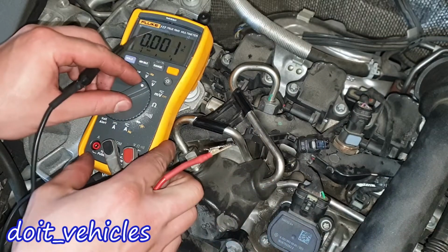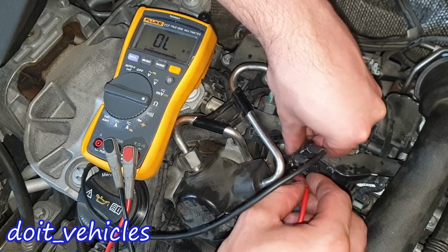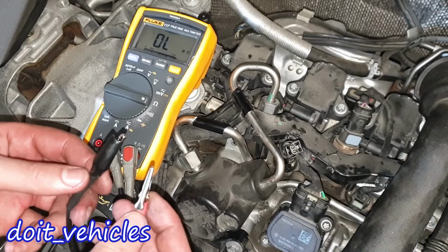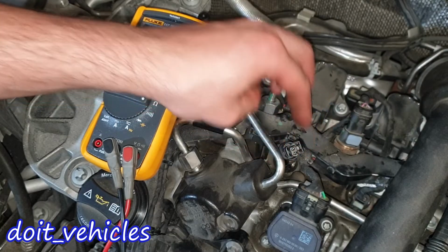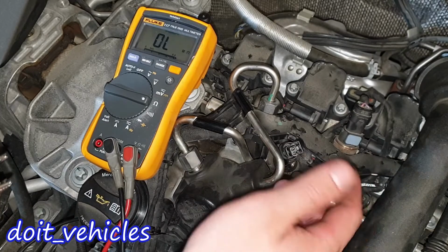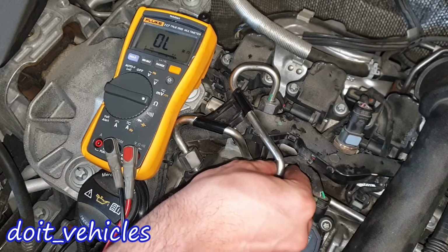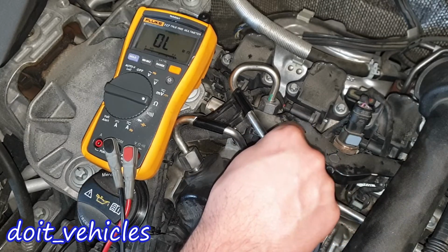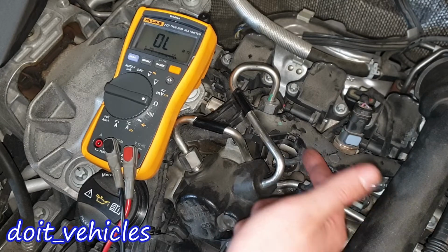Yeah. So let's turn this to ohm reading. We should find something between 3 ohms and 13 ohms. Okay, 1.5 ohms. It's going to be a little bit difficult to find a good connection in there, but if for some reason you've got one of these connectors, just plug it in and you have the wires out. A lot easier to do the test. So these are the values you need to read on a known good injector, around 1.5 ohms of resistance. However, this does not guarantee that the injector is not leaking or is not clogged.